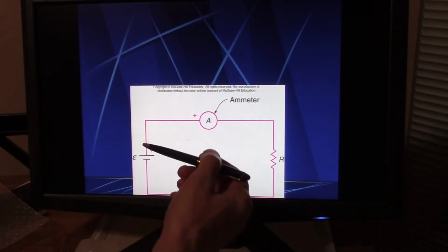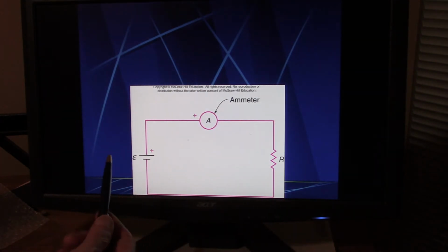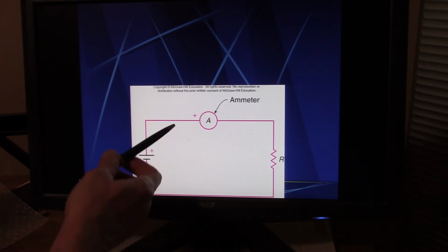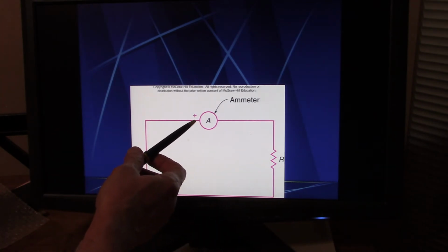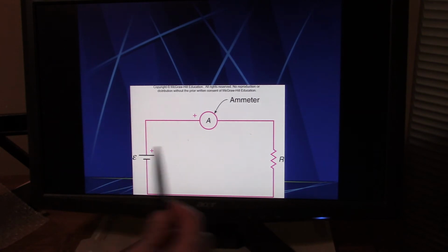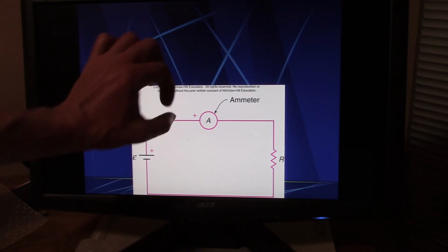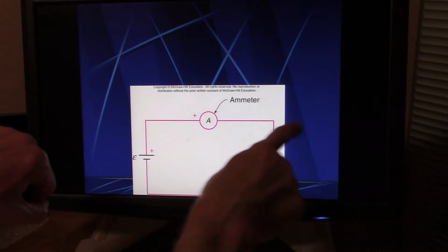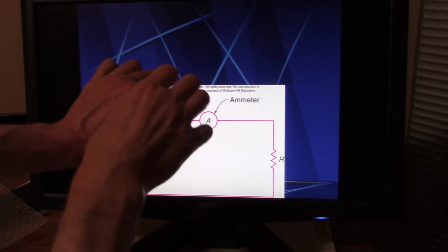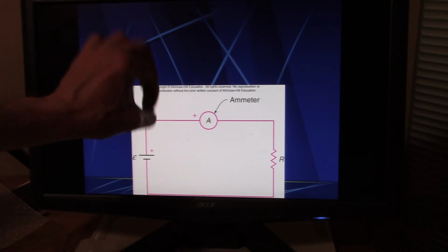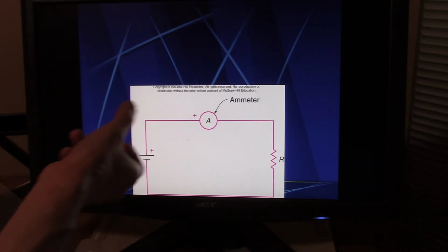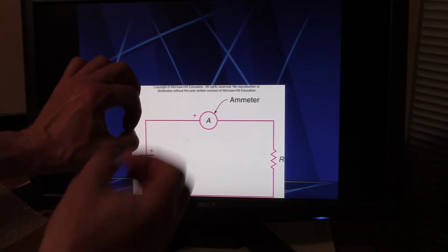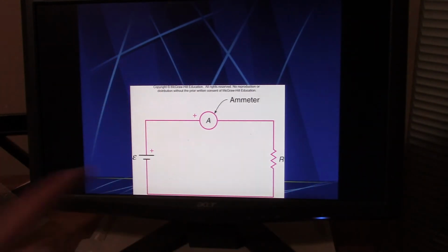So you're able to measure a current. You can either put a device where you're measuring the actual electrons going through, or you can just have a device that wraps around the wire, and the field caused by the electrons going through tells you what the current is. This is what they use typically in industry and automotive. You wrap it around the wire you're concerned with. You can measure the current because of the field.